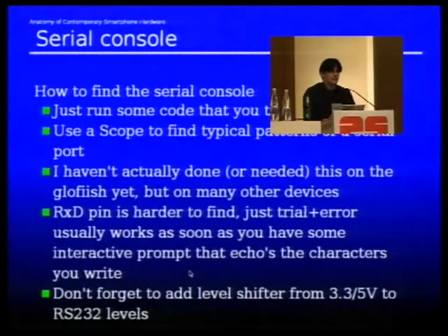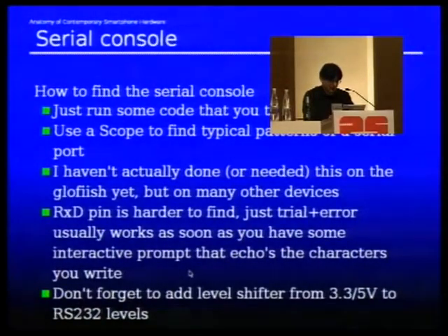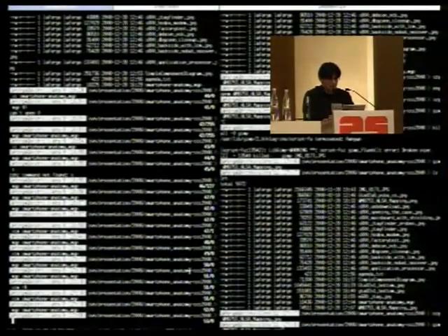Serial console is another useful thing. Anyone who's ever dealt with OpenWRT or similar projects knows it's always useful if you have the serial console to the device in question, so you can see what kind of debug outputs the developers left in the final shipping firmware image, and also see if there's any way you can interact with the device. So Linux-based devices or Unix-based devices, I would say in general, including BSDs or VxWorks or whatnot, typically have some kind of command line interface or console on the serial port.